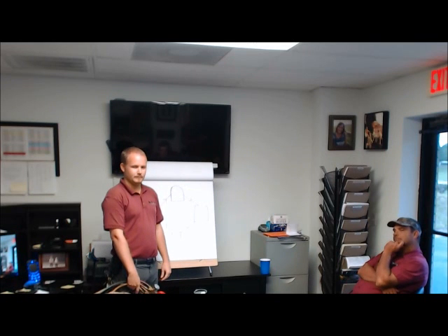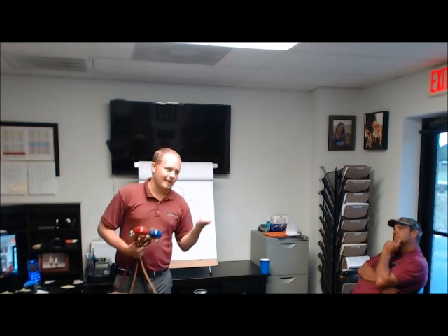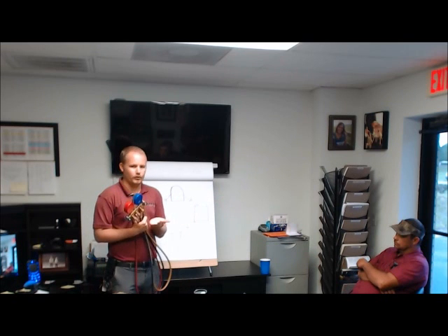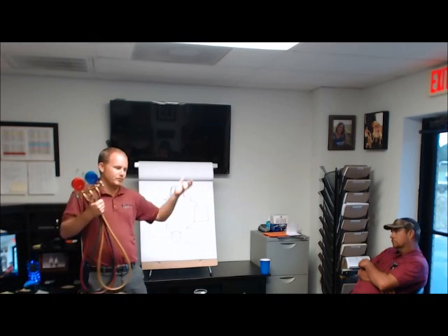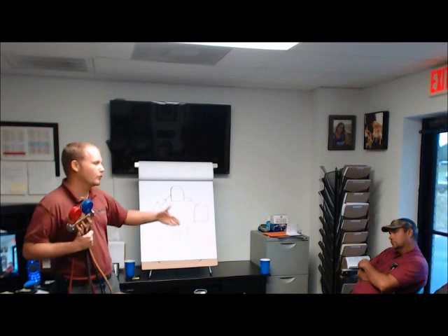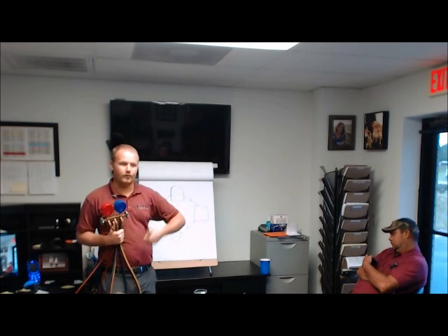As you increase pressure, you're also increasing the energy per volume. Correct. So you're making it hotter as you compress it. It has the same amount of heat it had before. You're not actually increasing the amount of heat, but you're increasing the temperature. Do you remember how we talked about that? By reducing the amount of volume that it has to operate in, you're exciting the molecules, so the molecules are moving faster. So it's directly proportional, meaning that the more you compress it, the hotter it gets. You can never turn something into a liquid just by compressing it, because it just gets hotter and hotter. So you've got to dissipate that heat in order to condense it. In order to turn it into a liquid, you've got to allow that heat to dissipate.